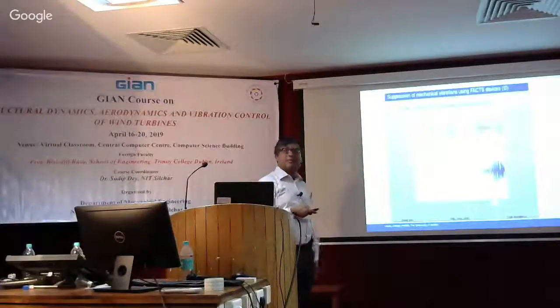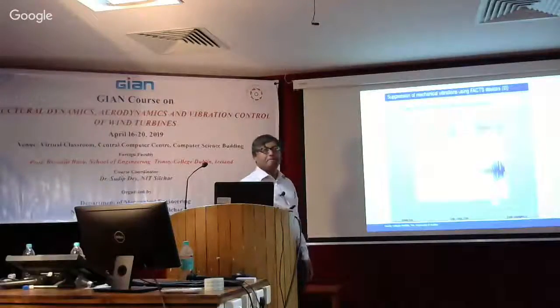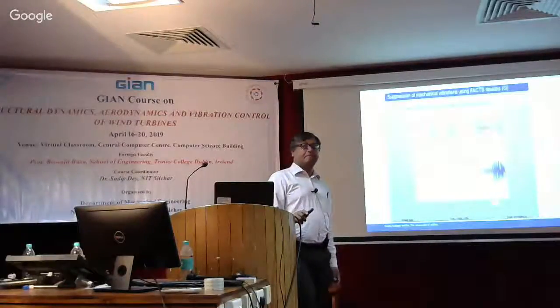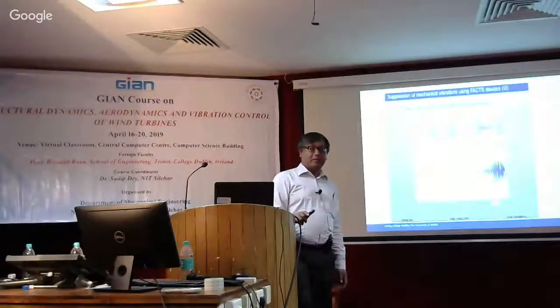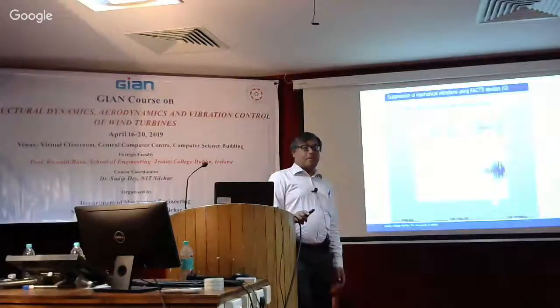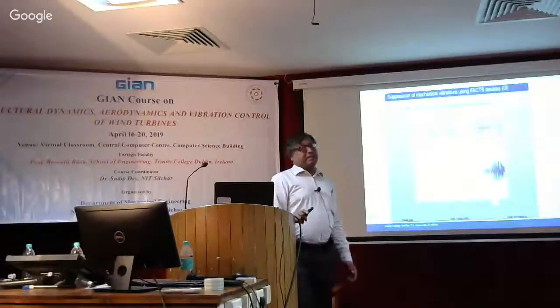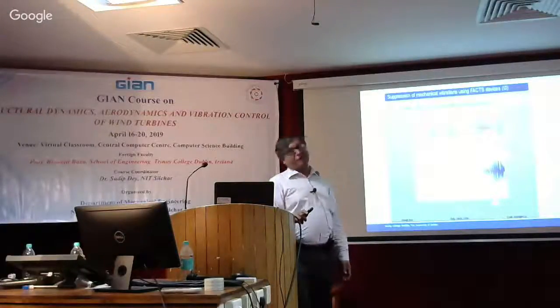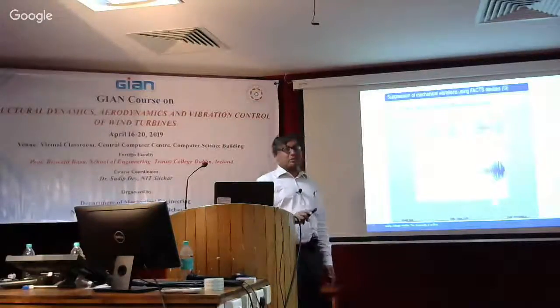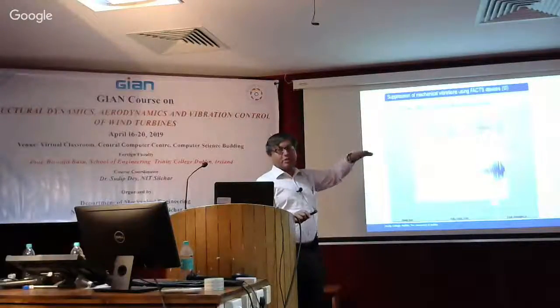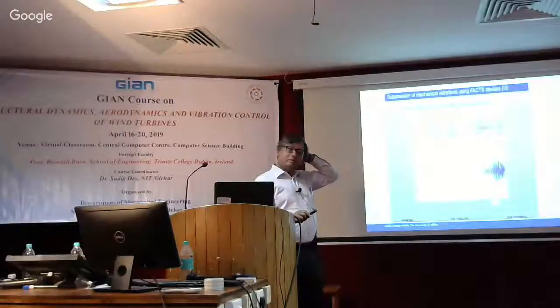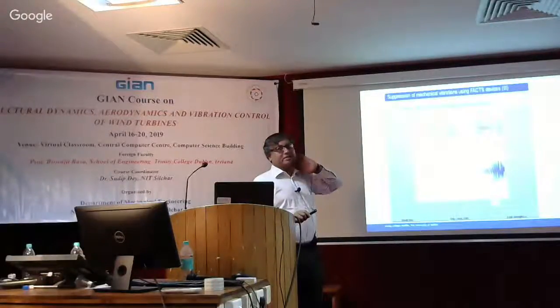Is there a standard or regulation that specifies the time duration? Because beyond that, the fault... Yeah, okay, perfect. Then you have to stop the operation anyway because of the requirement from the electrical grid code. But obviously, if you ride through the fault, what is the minimum time which we can override? I think it's 600 milliseconds or something like that.